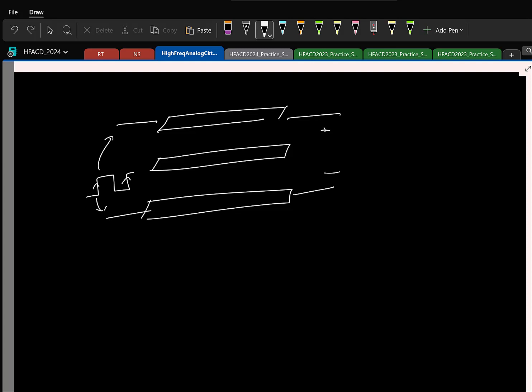Great. So let's look at the power supply issue. So now I know that my signal is like this, and one trivial way to generate this differential output is this: you take one block that takes in plus Vi by 2, you have an identical copy of this block, and what should I give here? Minus Vi by 2. This is one trivial way in which we can get this. So let's take this as an example and see what happens to the supply.